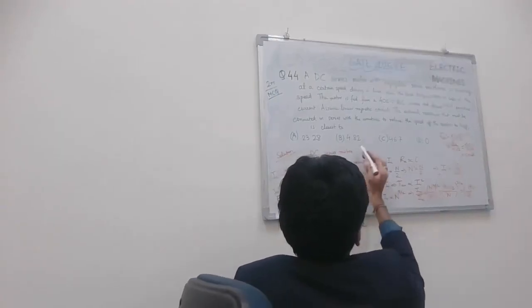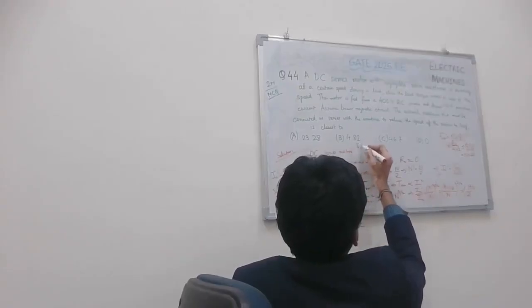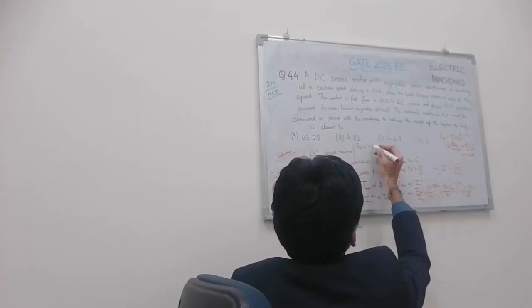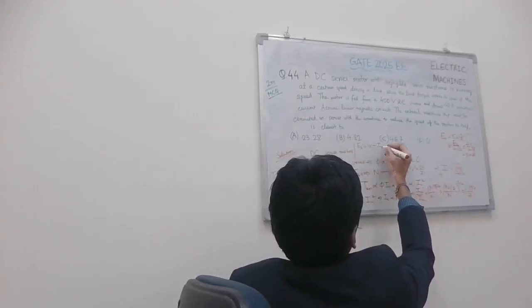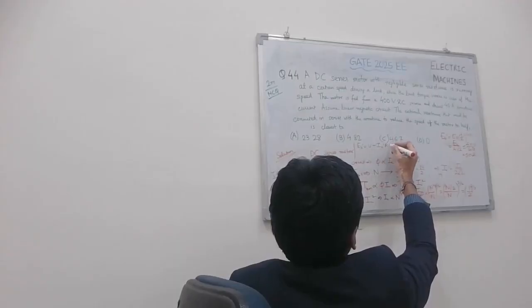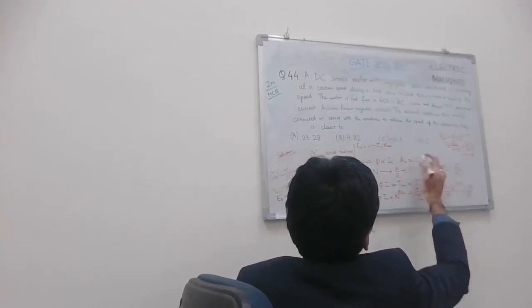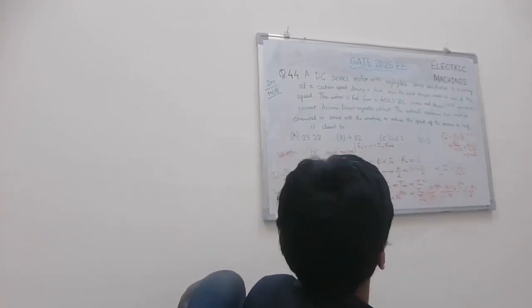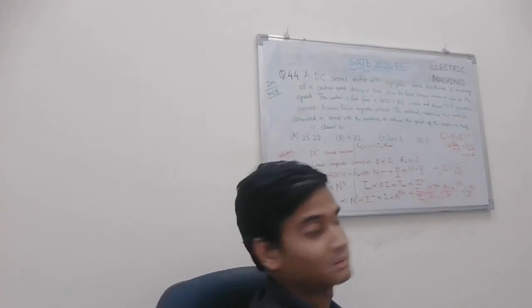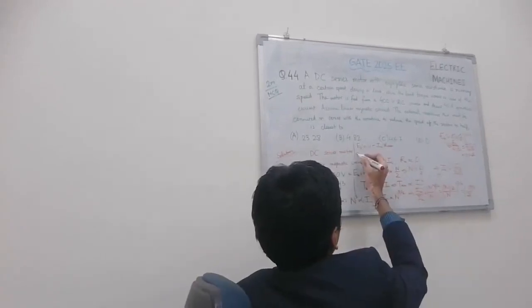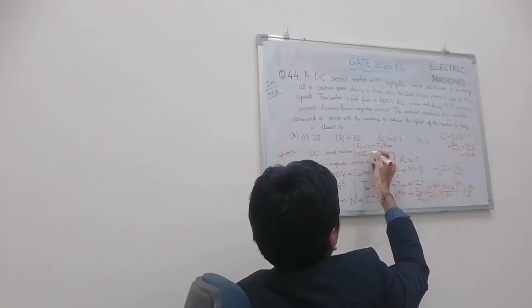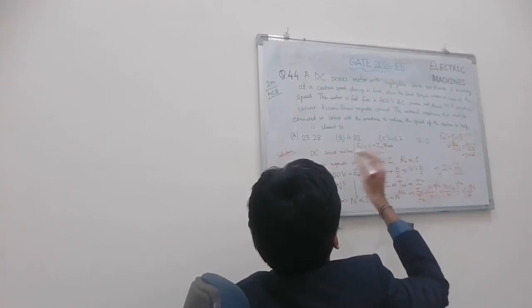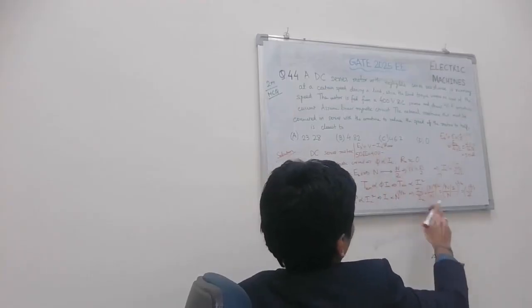Okay. So we can find the resistance from EB prime equal to V, the terminal voltage remaining unchanged, minus IA prime times RA external. RA is 0, but there is some RA external that needs to be connected in series. So EB prime, if you put 50 root 2, equals 400 minus IA prime, and IA prime is what we found in this case.